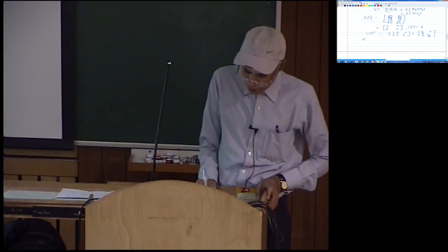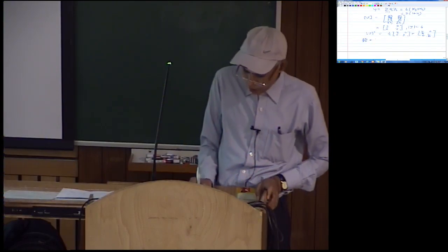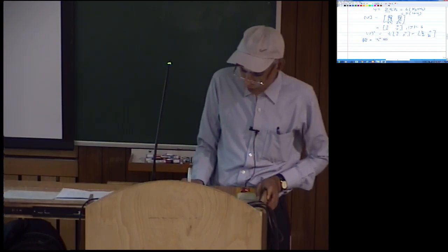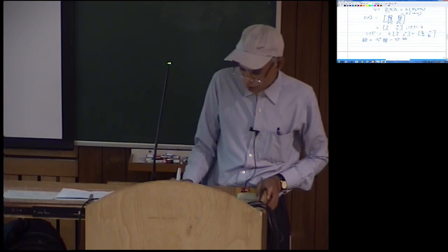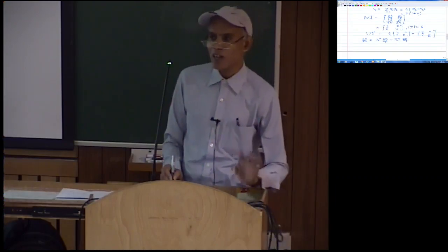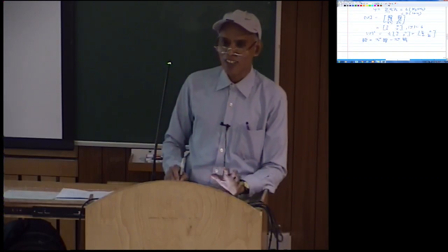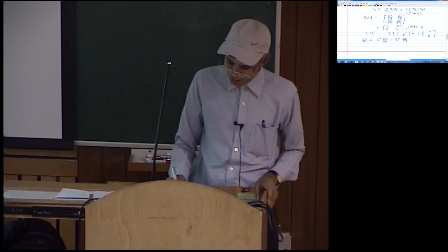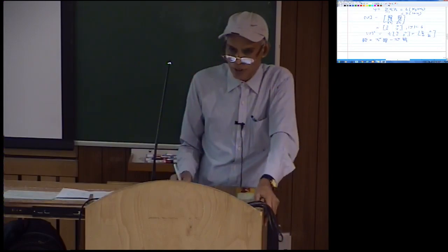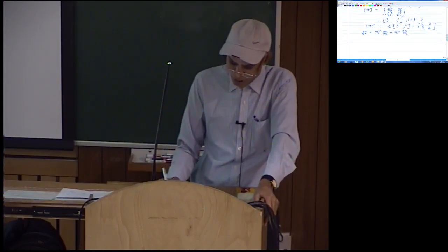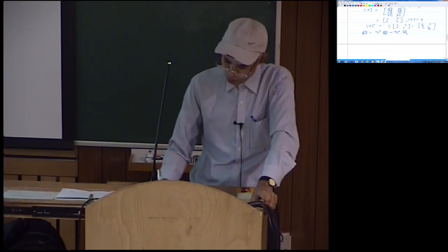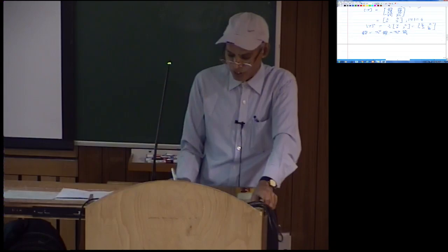Now how do we evaluate ∂N1/∂x? That is J11* into ∂N1/∂xi plus J12* into ∂N1/∂eta. You need to spend some time to understand things. It is not something to do just before the exam. Some of you didn't evaluate this correctly. It's actually a very simple expression, but you made it complicated because you didn't evaluate the Jacobian correctly, or if the Jacobian was correct, some of you didn't evaluate this final expression correctly.